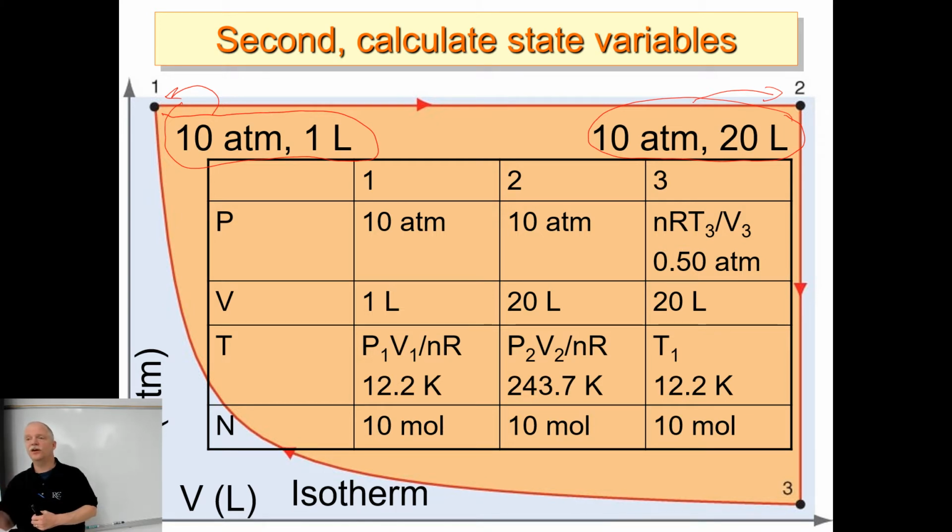So if I have the pressure and volume for point 1 and the pressure for point 2 on an adiabat, I can solve for the volume on that point 2 using these relationships. They're kind of strange because all 3 state variables are changing at the same time: pressure, temperature, and volume on an adiabat. Here, only pressure and volume are changing because the temperature is the same.